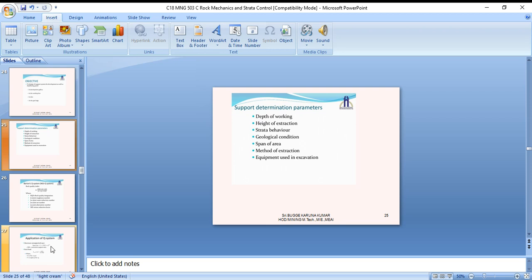In fact, there is a fundamental discrepancy between the basic assumptions introduced and actual conditions in the underground. These solutions are perhaps more useful for a demonstration of the influence of individual parameters. For very narrow openings, the theories involved take into account the complete static weight of the superincumbent rock, with friction according to the correction in the theory.